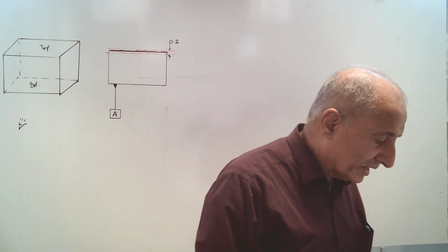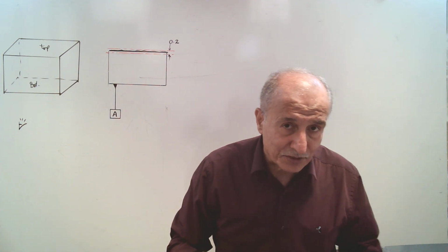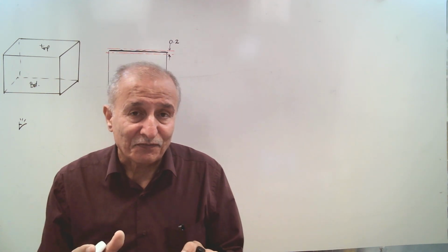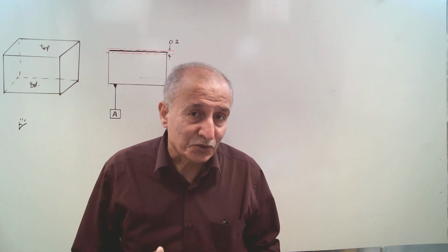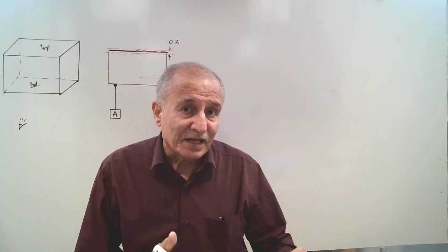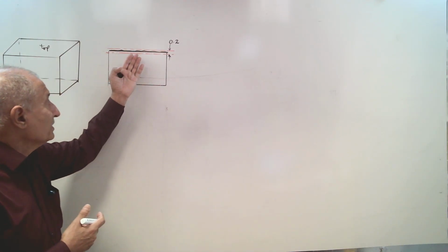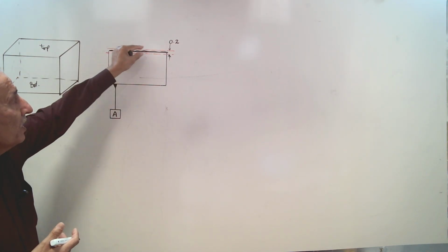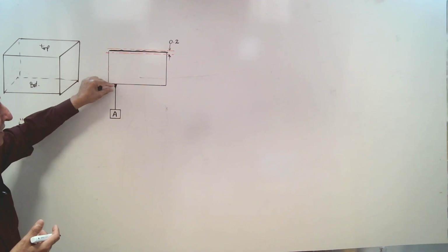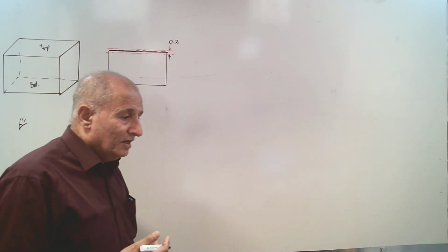We give this allowance to the manufacturer, because I know that you cannot make perfectly parallel surfaces. Then I give a zone, an allowance for your errors. And the real surface must lie within this tolerance zone, and this zone is parallel to datum A. How can I show that I mean this?